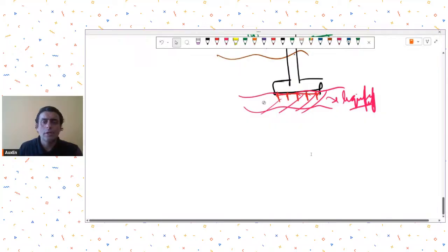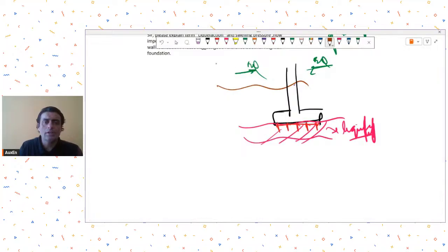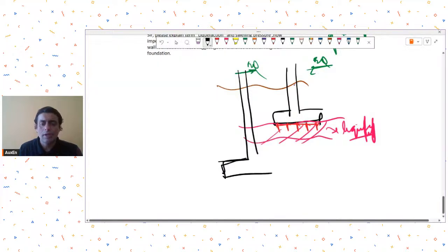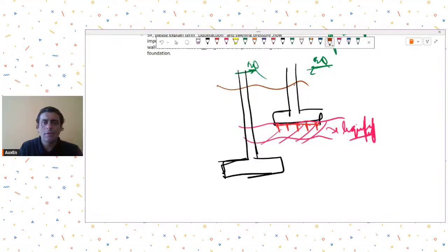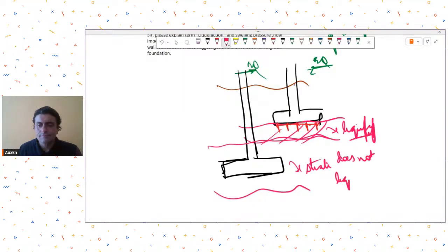Generally the geotechnical reports that we get tell us about the different soil strata and the possibility of liquefaction. So what we generally do, if there is a strata which has a tendency to liquefy, is not place the footing at that level, and take it to a deeper strata where there are no chances or tendencies of liquefaction. So let's say this strata does not liquefy, then you would like to keep your footing on this strata. So this is what is meant by liquefaction.